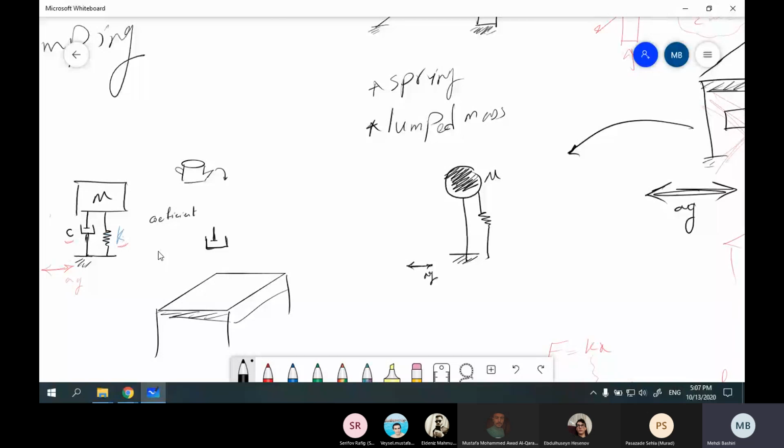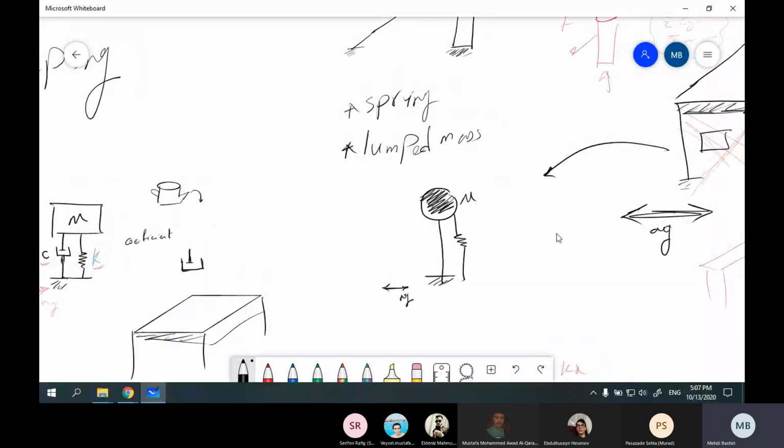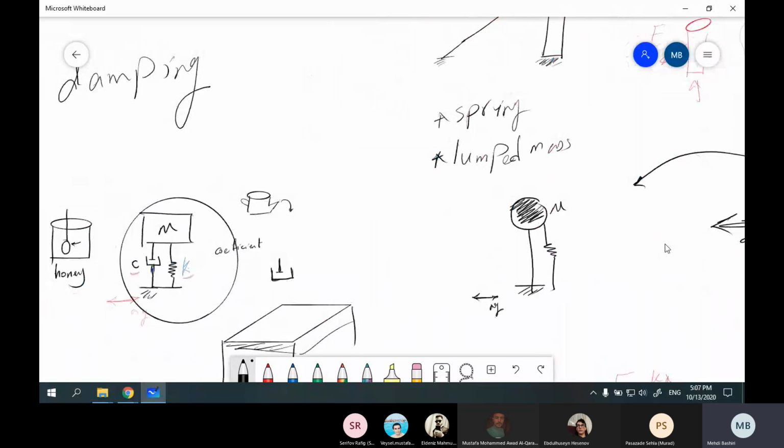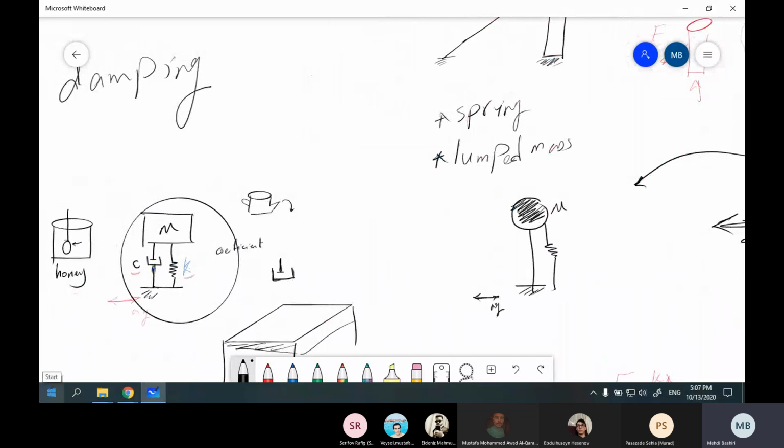Instead of bricks, connections, anything that absorbs energy, we just have this dashpot, or damper. Instead of this complicated mass, we have this box, and this is our model for this structure. This is the simplest model. You can't design a tower, for example, a flame tower, using this model. But you can design, for example, a 1 or 2 story building with this model.